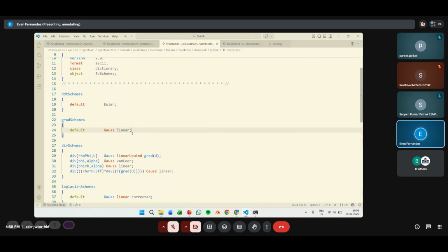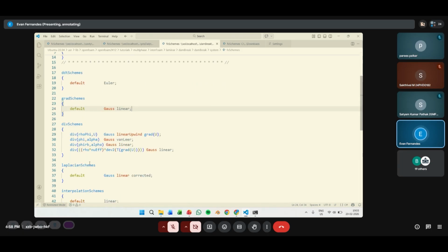And a key difference in multi-phase simulation is that you will have something known as alpha. You can also check all of these additional parameters. We look at all of these when you're doing a proper multi-phase simulation. So you have some additional parameters such as alpha dot water for interface tracking. You will have some additional parameters that you keep in mind for multi-phase, because in multi-phase you would have two particular phases, or two particular things going on at a single time. So you might also have two fluids, say one is oil, one is water. Those types of simulations require some additional parameters, and those things are mentioned over here.